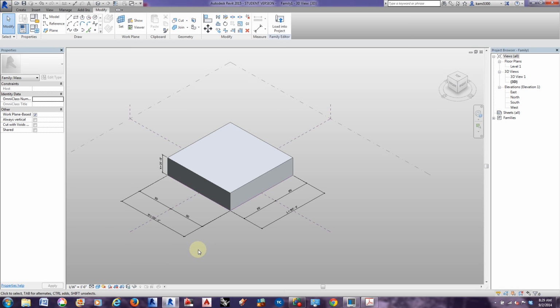So you can create a length and width parameter without actually assigning them to a dimension. So there is no dimension that makes that flex. So you're going to have to dissolve the shape, and then dimension from here to here. And then apply to that.